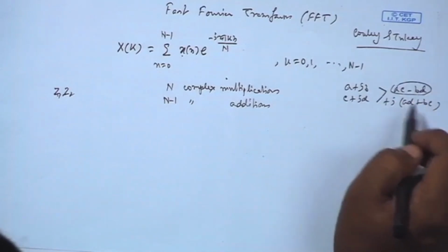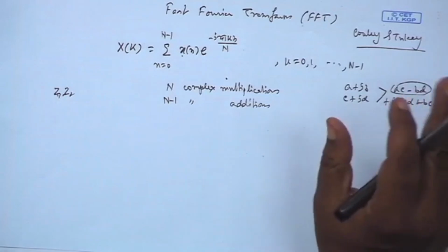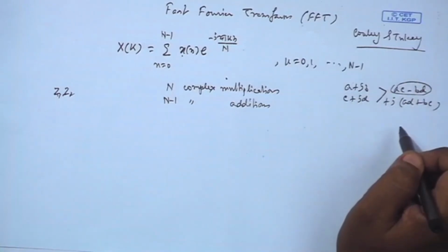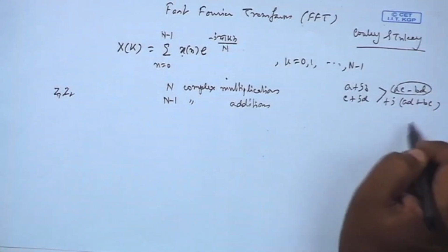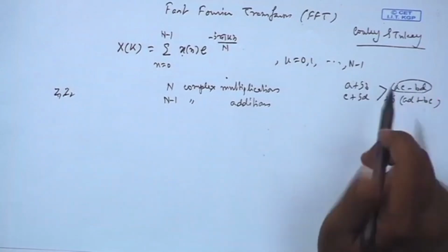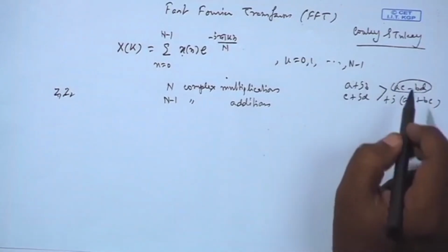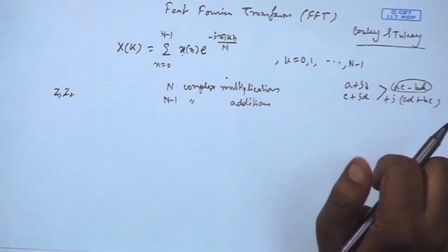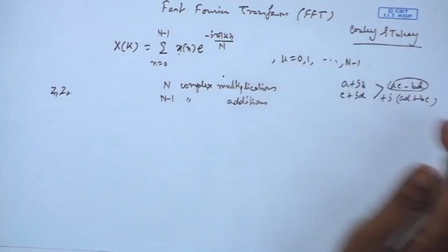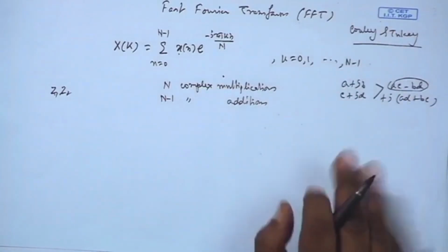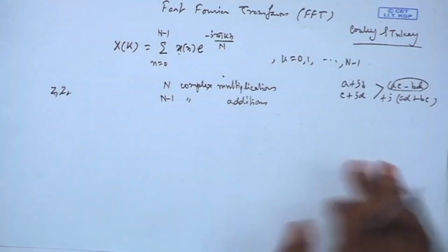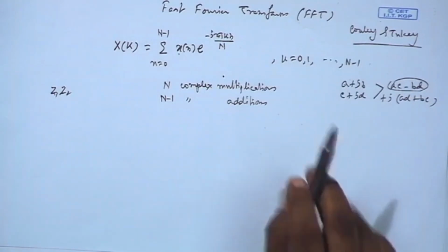In fact, totally you need four multipliers, but by some tricks which I am not showing here, you can bring it down from 4 to 3 by introducing some additional terms. So, additions will go up, but whatever, this is complex multiplication. So, complex multiplication can have 4 or sometimes 3 real multipliers, because all your multipliers in hardware will be real multipliers. You will be putting them in some format and considering something to be complex, but all multiplications in real hardware will be real multipliers using real digital hardware.